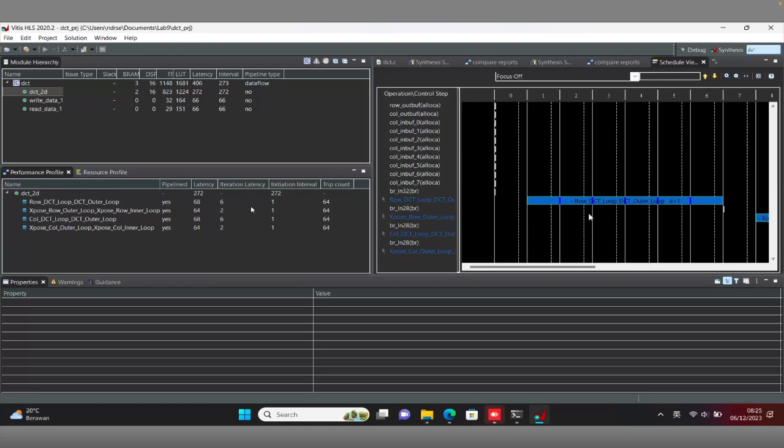I think this is our lab today, so you can follow this improving area. The first thing that you need to do is improve the memory usage using array partition. The purpose of array partition is improving the memory usage in your device, and data flow is improving the latency.